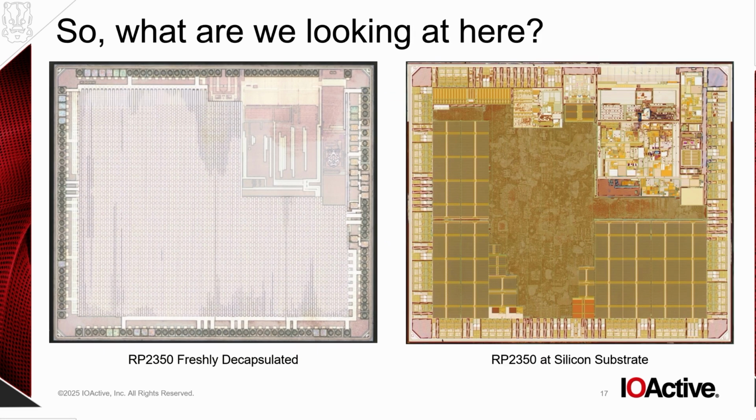So just a bit of background about semiconductor devices, just to try and explain what it is that we're actually looking at here. I mentioned that's a decapsulated chip, which it is. Essentially that is a fully processed chip, and that would still work if it was connected to the outside world. You can see these little circles around the perimeter of the die, and that's where the bond wires would have been, but we've taken them off. So that chip is untouched, undamaged, would still work.